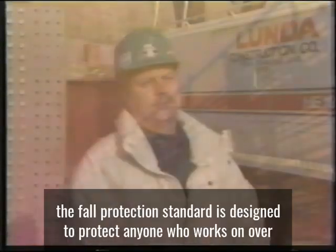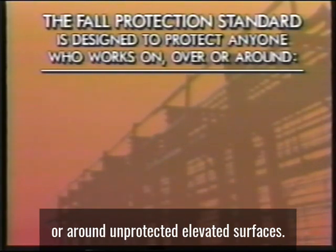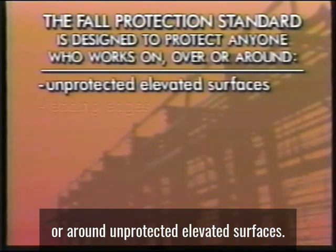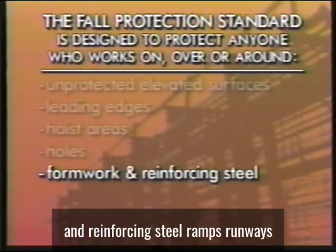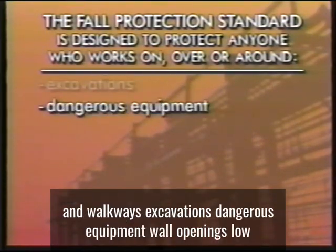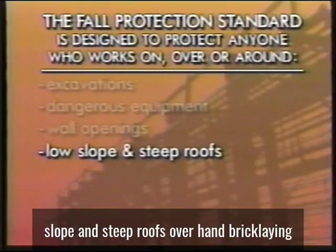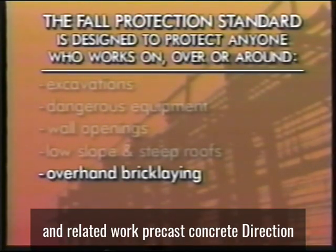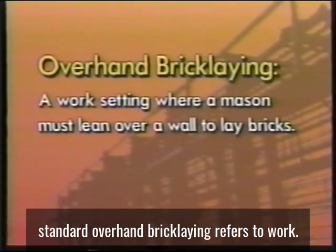employee from falling. The fall protection standard is designed to protect anyone who works on, over, or around unprotected elevated surfaces, leading edges, hoist areas, holes, formwork and reinforcing steel, ramps, runways and walkways, excavations, dangerous equipment, wall openings, low slope and steep roofs. Overhand bricklaying and related work, precast concrete erection, and residential construction are also covered by the standard. There are a few definitions that will help you understand this standard.